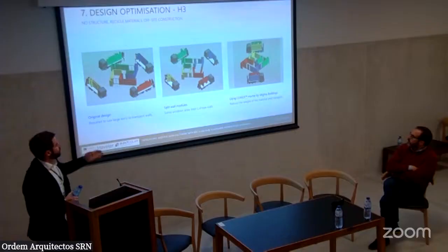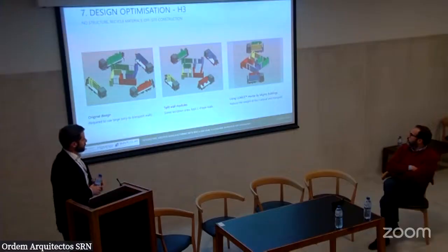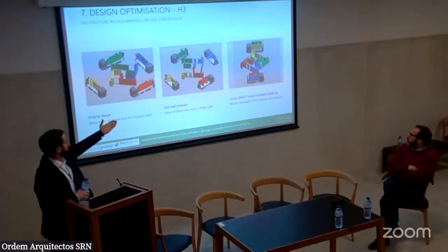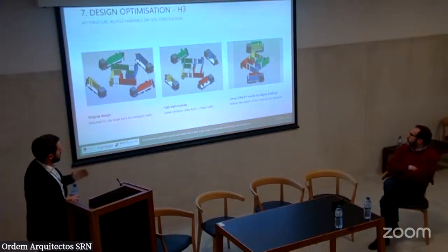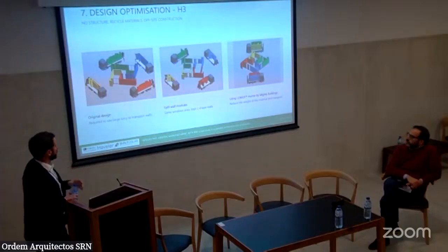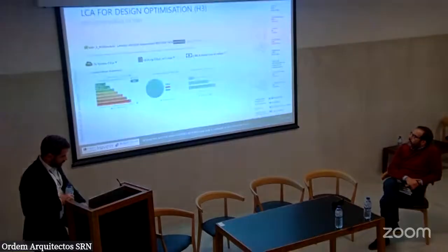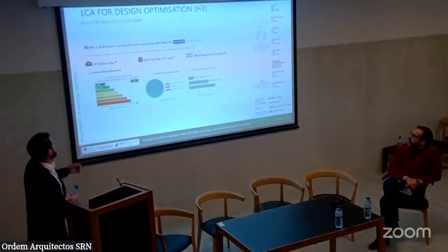Or even, if you go further and use a lighter mortar which weighs less, for example the mortar used in the USA by the Mighty Building Company I just showed, we can reduce the CO2 emitted with the transportation of these printed walls from the factory to the site. So this was another study to optimize, which automatically gave us a classification of A.